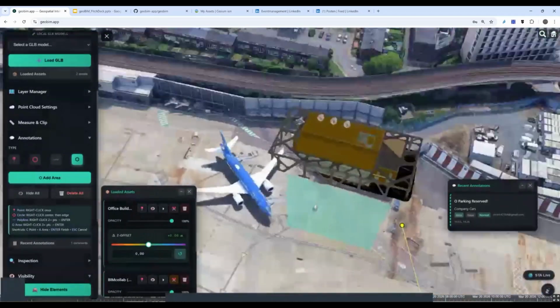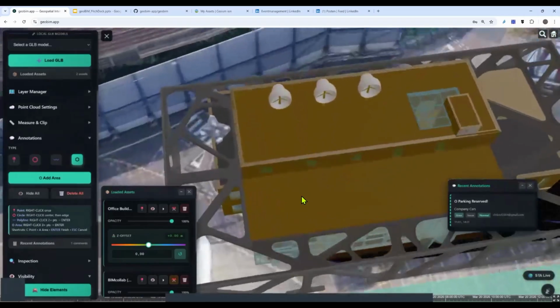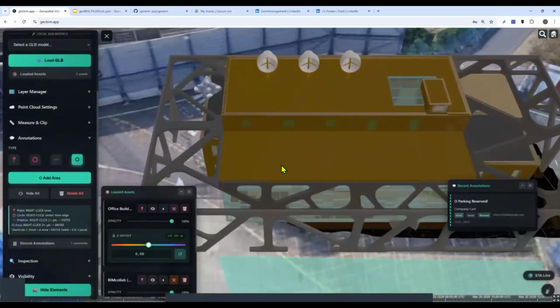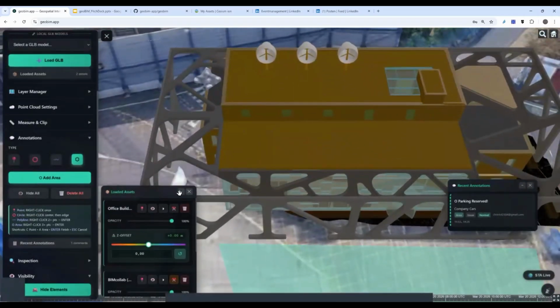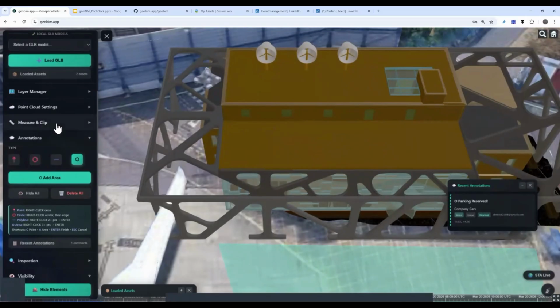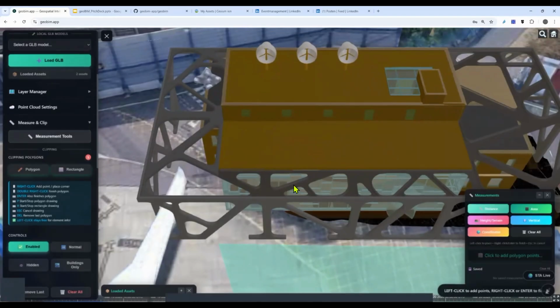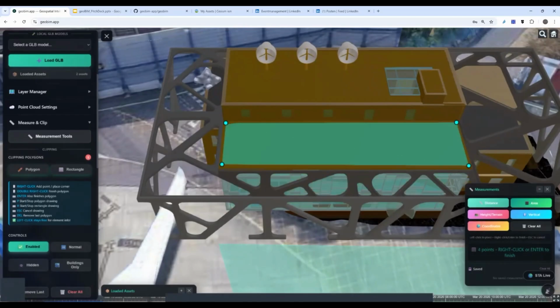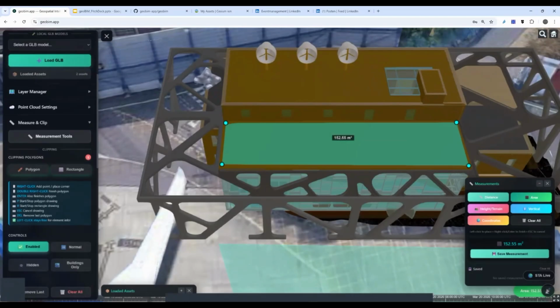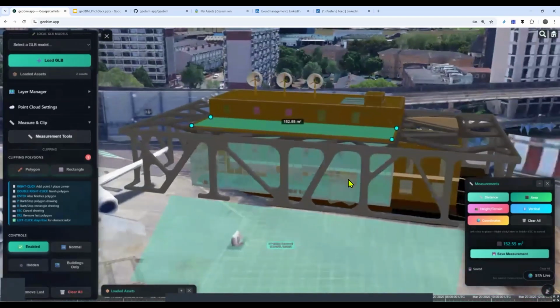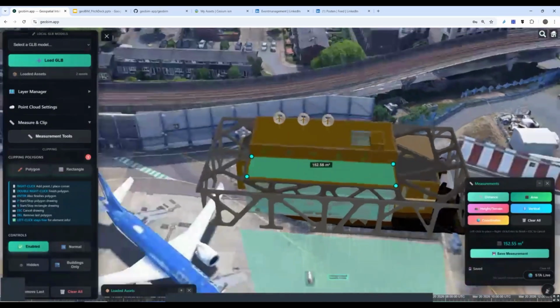And then we'd like to measure the area on top of here, because we maybe want a terrace up here. Again, we use the measure clip first, and we say measure, and then area, and then it will ask to left click the points, and we see how big that space up here is. And that's 150 square meters, and that should be sufficient to place a nice little terrace up here. Okay, so we have that.